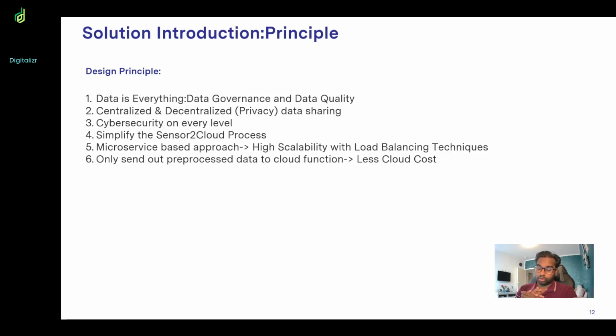On-premise, we need to make sure the security level is at its highest, and the sharing of the data should be one way, because we don't want to enable commands or open up the operation of the boiler system from the internet itself. There is a safety risk. To address this, we have to make sure the connections are certified, encrypted, and enabled with multiple levels of authorization.